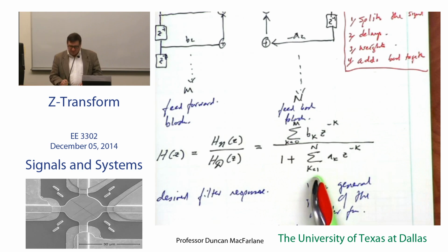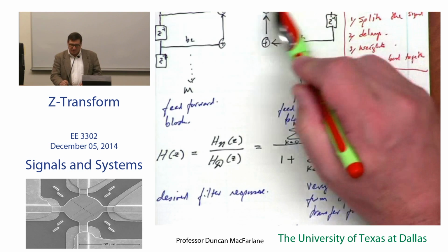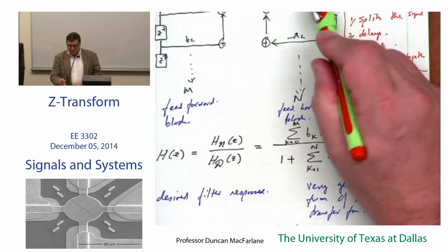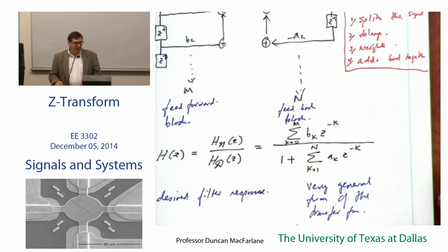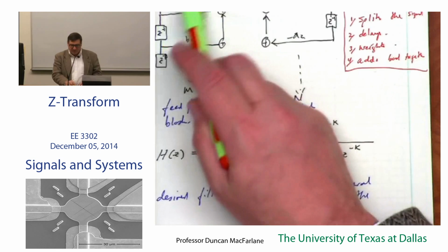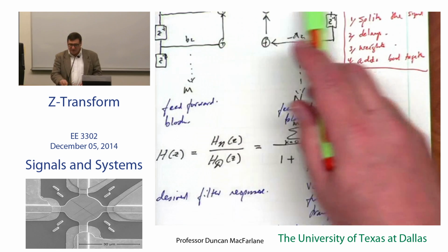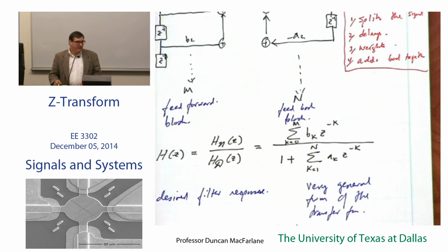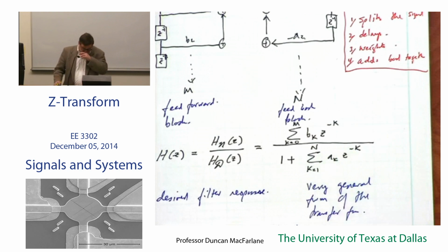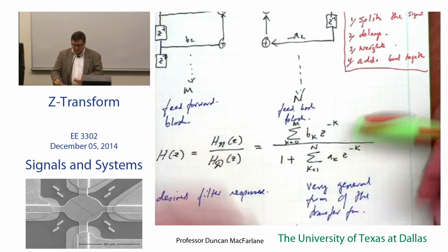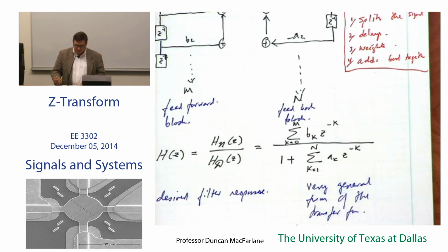And then we start this summation at 1. Okay, so there's always a unit delay here, and this branch here is this 1. Okay, and so the overall gain of the filter is b naught coming through there. Okay, so just a small funny way we choose to write those polynomials.